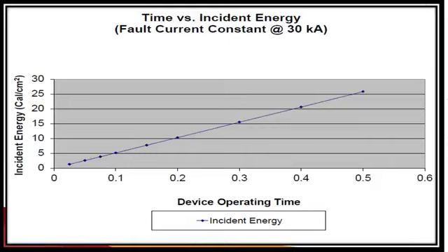They might be offering some expensive solution to reduce incident energy, but now you have this knowledge that the incident energy can be reduced if you play with the device clearance time. If they have marked a high device clearance time, that means the incident energy will be higher at that location, and they are advising you some other solution rather than playing with this device clearance time.